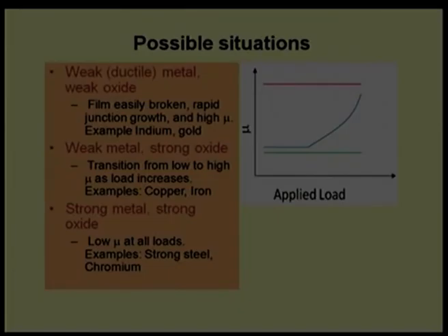Whenever we design any tribo pair, we should aim for this kind of layer, so that we can get a low coefficient of friction. However, if we want a high coefficient of friction, then we can choose the first case, but in that case the wear rate will also be very high, and then we need to provide appropriate action or appropriate tools to get a solution.